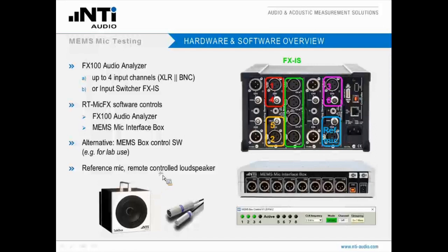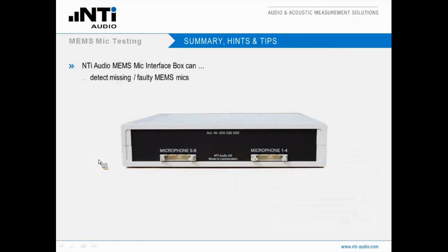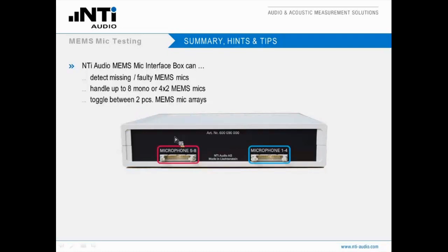One more slide on the MEMS mic interface box. Keep in mind, this box from NTI Audio is able to detect missing or faulty MEMS microphones. It can handle up to 8 mono microphones or 4x2 MEMS mics. And we have 2 connectors here for 4 mics each, and we can toggle between these 2 connectors if we like.